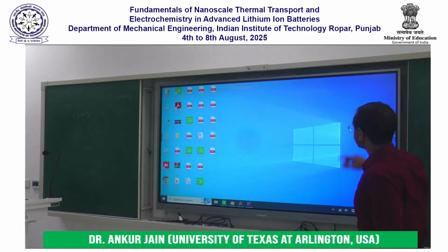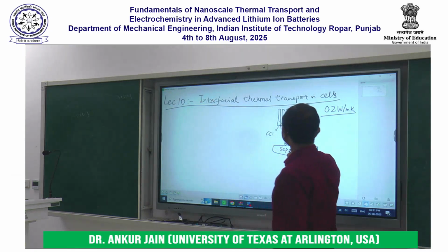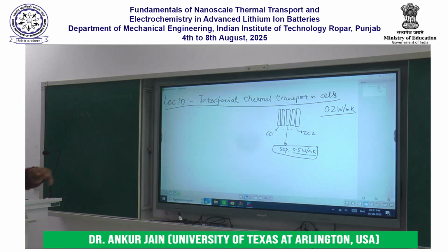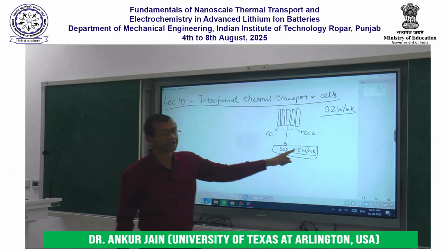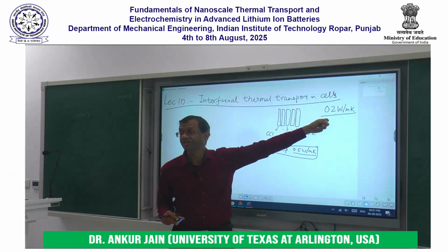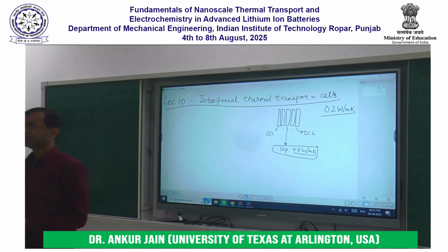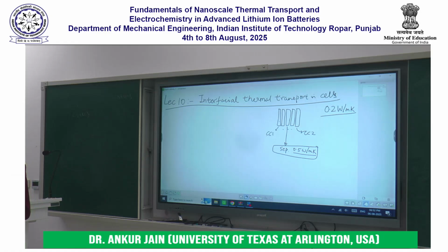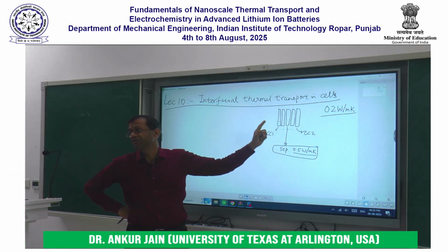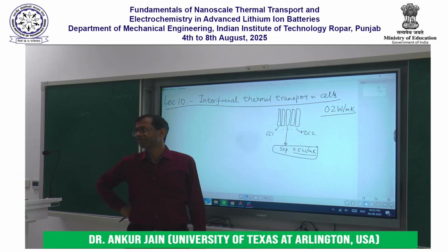So I guess the long and short of it is that even the separator has a thermal conductivity of 0.5 watt per meter Kelvin. Using the paper that I had just presented, the measured value of the thermal conductivity of the separator turned out to be 0.5 watt per meter Kelvin, and it was a little surprising because the thermal conductivity of the cell itself was even lower than that of the separator. So from there we started asking ourselves, what do we need to do in order to measure the interfacial thermal resistance of this body.